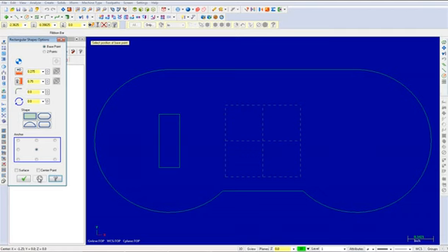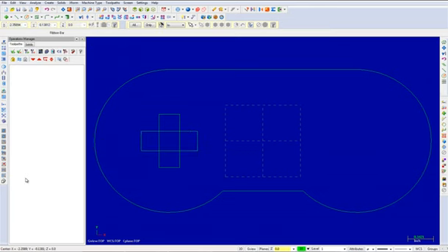In the Rectangular Shapes Options dialog box, click on the icons in front of the width and height to lock these values and enter a value of 90 degrees in the rotation field. Now select the same center point as shown. Once complete, select the OK button to exit this command. Your geometry should look as shown.